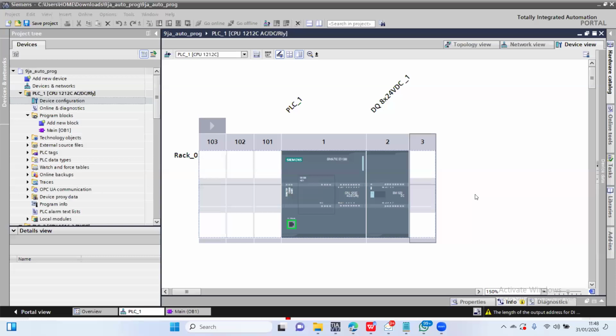For the RSLogix 500 series, for example, if you are using a MicroLogix 1400 and trying to use Modbus TCP, I believe that is only available from, I think, version 11, and you need the MicroLogix 1400 Series B PLC. So there are sometimes only certain features that are available on certain firmwares for a particular PLC.